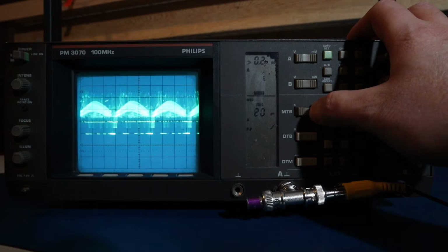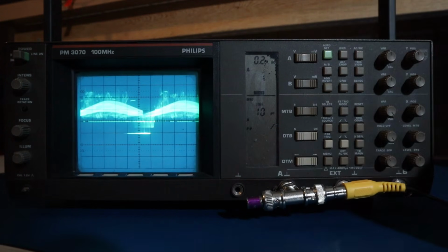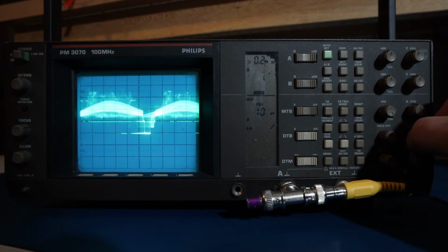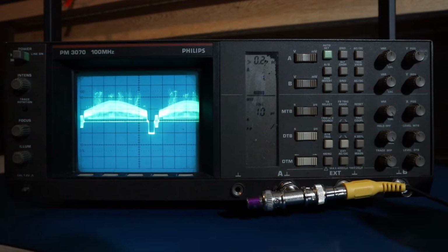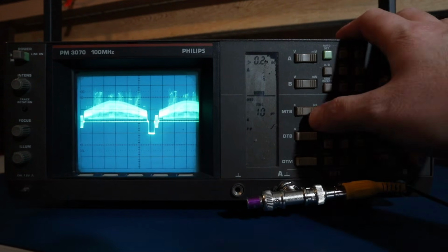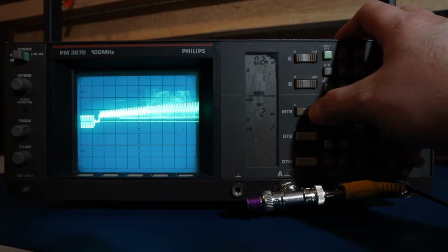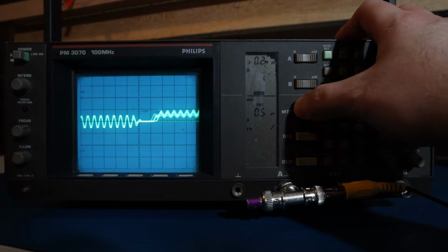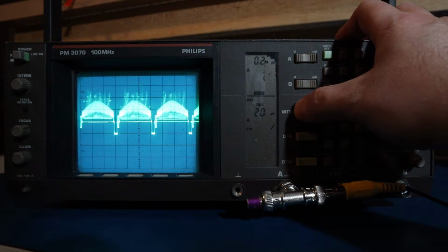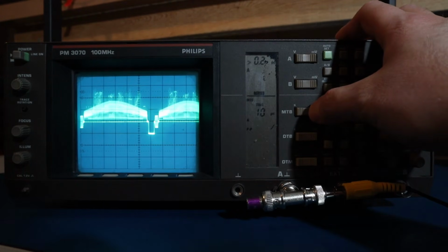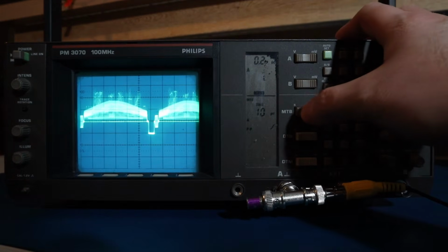I'll zoom into a line at 10 microseconds per division and adjust the trigger level. Now we're locked in. And we can zoom in to check out the color burst or whatever. So, not as impressive as delayed time base or video triggering, but it still gives you a basic look at